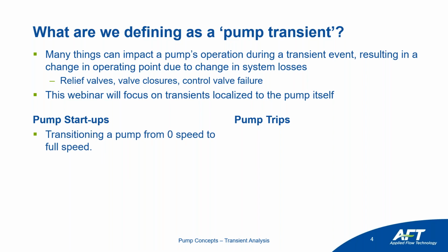A lot of the startups that we're going to be modeling are considered uncontrolled startups. So imagine you have your motor connected to your pump and you just flip the motor on and you let it approach that steady state operating point essentially as quickly as it can. This is different from a controlled startup where you may gradually ramp up the pump, which we can also model in the software. And a lot of the different modeling approaches will be similar, and it's just knowing how your system is set up and how you're designing your system to inform which way you're going to design it.